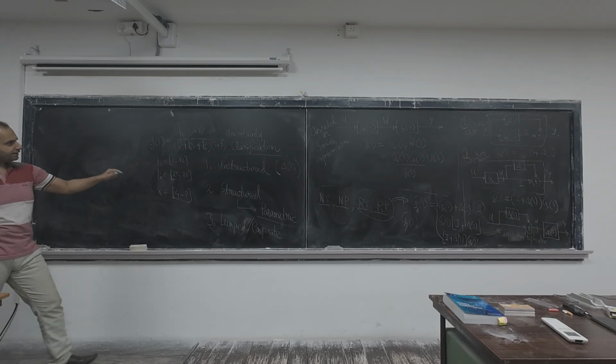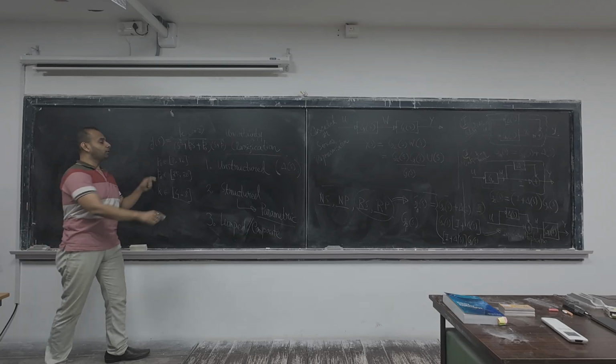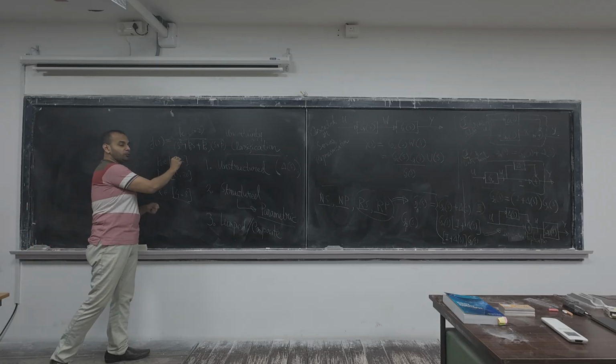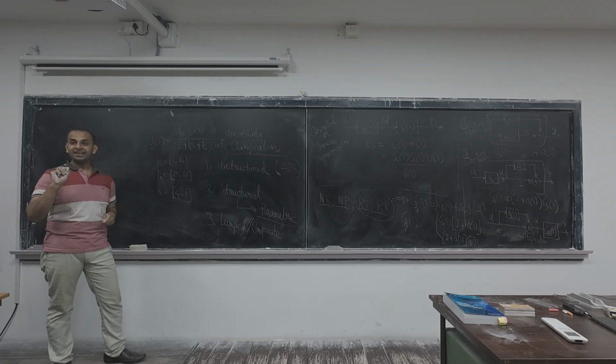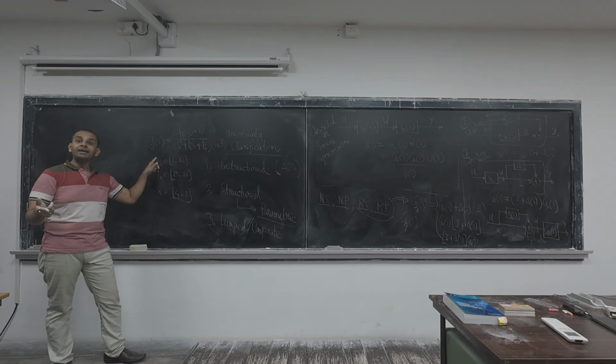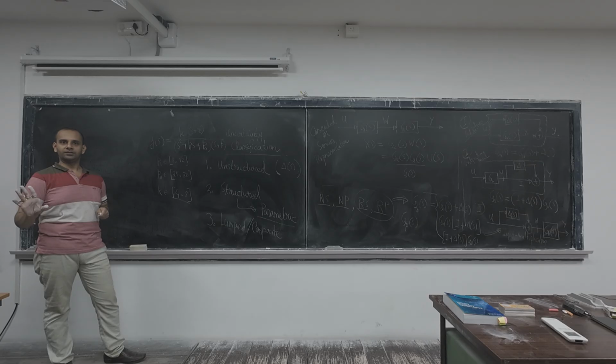So once again, in summary, parametric uncertainty is structured because due to this bounded perturbation or variation, there is no change in the structure of the original model or the transfer function, keeping aside the possibility of pole zero cancellation, right?